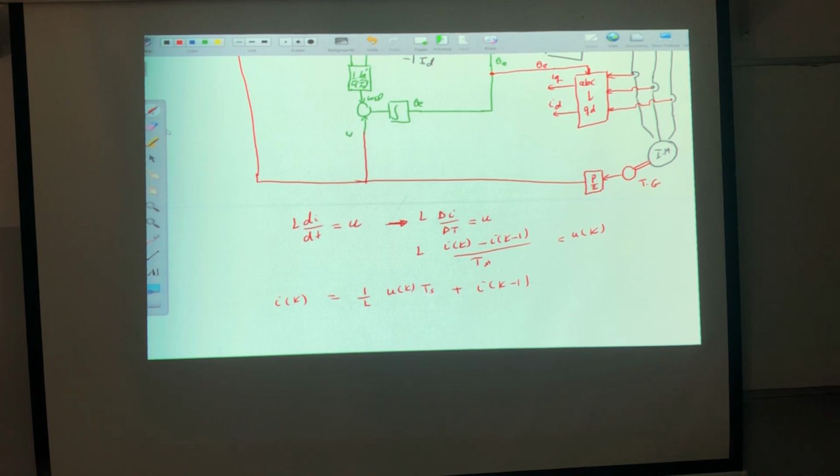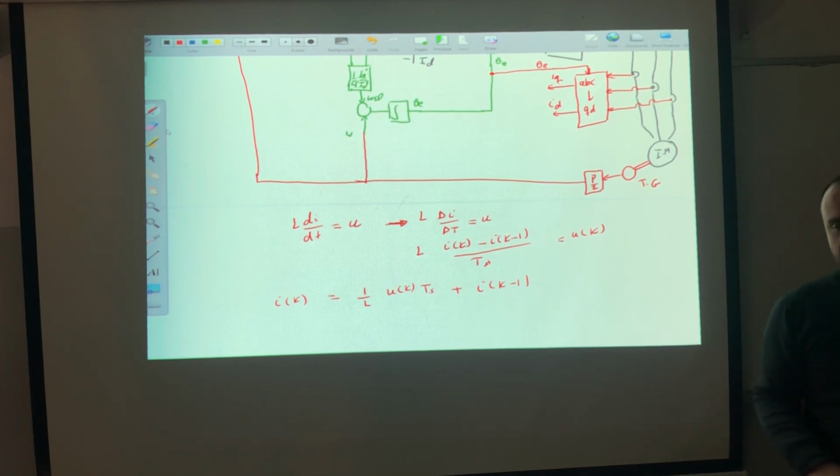Alright, just a minute. You are missing a point. If I recall back to the DC controlled rectifier or chopper, we stated that we have two methods of current control. The first one is hysteresis current control. The second one is PI control plus pulse modulation. Now, when we design the controller for the DC drive system, we stated if the current controller is hysteresis, then the only thing I need to design is what? The hysteresis band. That's it. End of the day, you cannot do anything else.